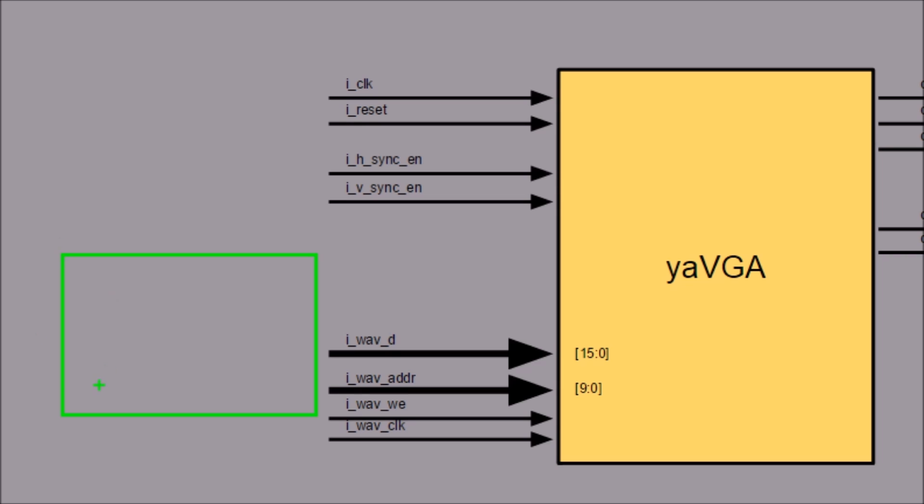So pretend this is your VGA monitor. Address is going to determine how far along the x-axis you are, and data is going to determine where the point is plotted vertically. If you were to increase the address while you are increasing what you write to data, then you would get something like that, where you would start from the top, 0, and go to the other extreme. Now, when you want to write data to a specific address, you need to have the write enable high. So if you want to write data like 1F2E at address 300, you would need to set 1F2E here and then 300 here, but then you would also need to raise write enable high. Otherwise, the data will never get saved to that address.